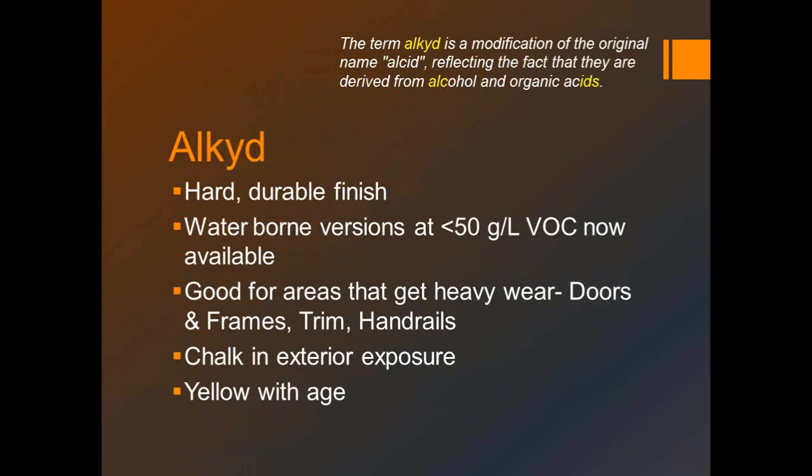Any place where you need a hard, durable finish. One of the places that I've always liked to specify alkyd paints on the interior in particular is doors and frames, because they get handled so much. And with acrylic paints, you can get some softening, and they seem to pick up the oils from people's hands and soil more, and they don't have quite the same cleanability. And you are spot on with that. I would totally agree with you.